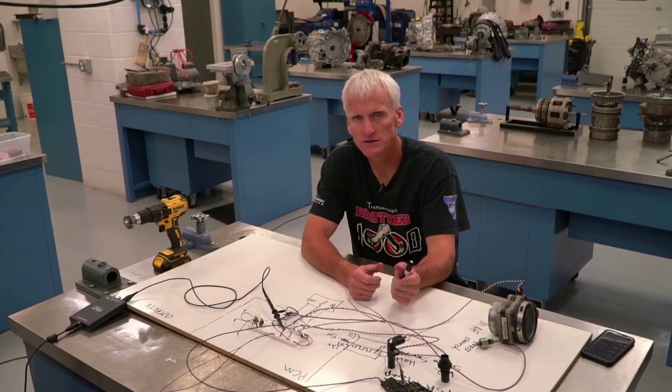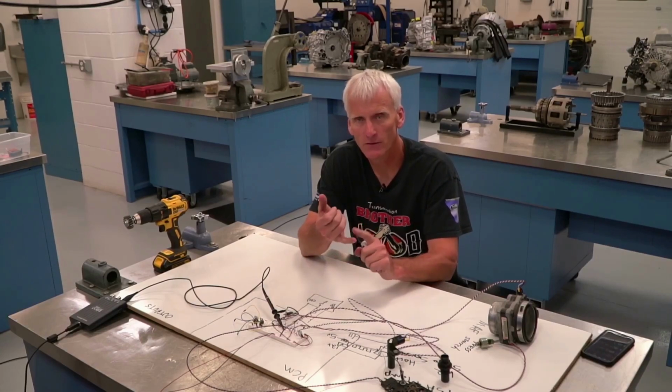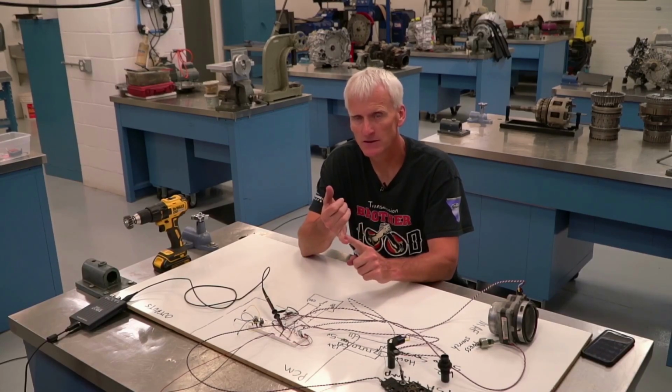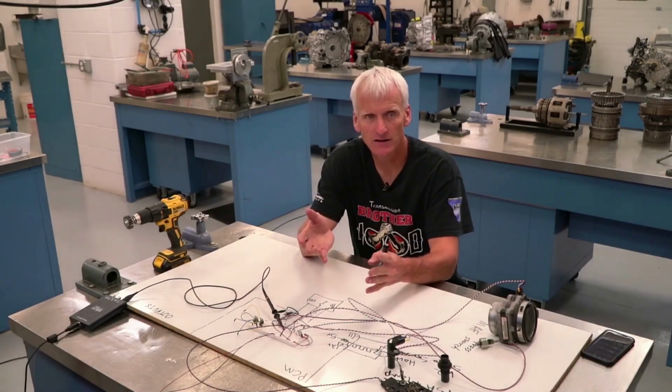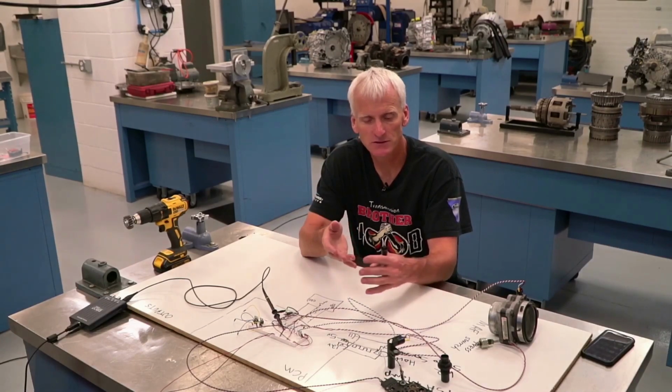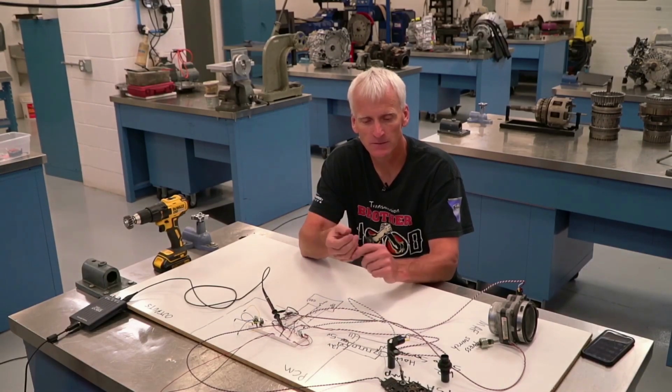And think of our inputs. Some of them are extremely important. Our range sensor is important because the module is going to need to know if you're in park, reverse, drive. Otherwise, it's not going to give you gears. If it thinks you're in reverse, it's never going to control multiple speeds. Or if it thinks you're in park or neutral, it won't do that either.